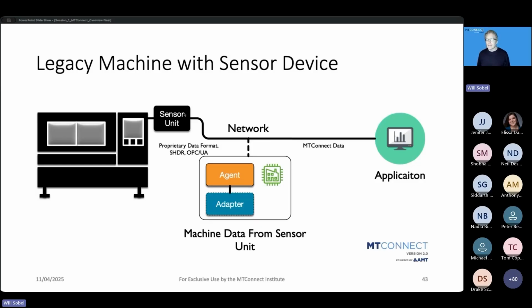You can then connect that to the various different terminal blocks in the machine. I'm talking about a machine, let's say, from the 80s. And those relays will then send you the basic states of the machine. So those are probably your modes, your stack light, your execution states, whether it's ready or active, those kind of things. And so we can support anything going all the way back to manual machines by just sticking a little box next to it and monitoring certain states of the machine.